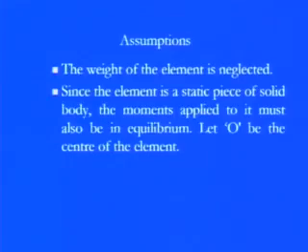We are not considering the weight here, because if we consider it, due to the gravitational acceleration there are some more stresses, and this gives a non-uniform stress distribution. Then defining the stress in either Cartesian or cylindrical coordinates is very tough and complex, because the stresses are different at different points: the displacement of each molecule is different, and the resistive forces are different because of the self weight of the element. So the first and foremost assumption is to always neglect the weight of the element.